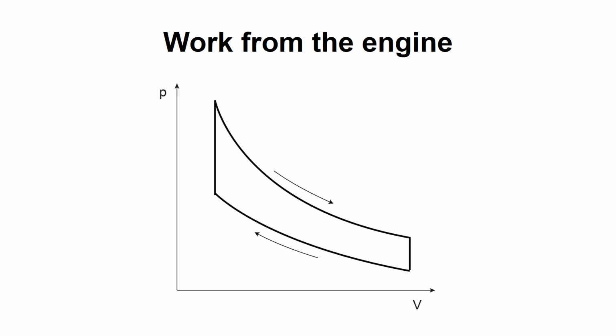The work from an engine can be calculated using thermodynamics. A first approach often looks like this. There are no heat losses and combustion is assumed to be instantaneous. The work from such a cycle is the integral of pressure multiplied with volume change, and the work produced is given by the area inside the pressure trace.